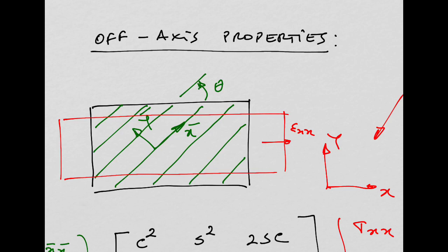For example, imagine if you have a laminate with 5 laminas or 5 plies, all with different orientations. We always apply a load in the global coordinate system, right? But because the plies have different orientations, we need to do this stress transformation for the different orientations of the plies, and then we need to see, for every single ply we have in our laminate, if there is one that fails, it will compromise the entire laminate, right?